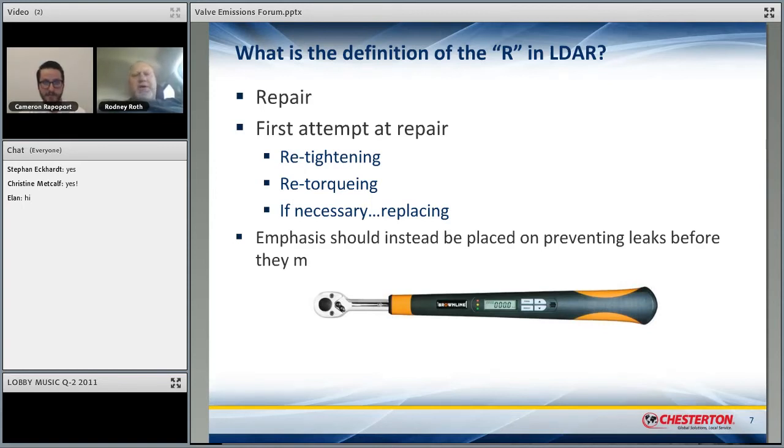And also, too, you have to understand that they may be on quarterly monitoring, and once it becomes a leaker, it becomes monthly monitoring. So instead of doing it every 3rd month, you're doing it 3 times a quarter. Right. You have a lot of chronic leakers. You can drive the frequency of your monitoring more across your entire plant, right? So if you have a lot of chronic leakers, you go over a certain threshold and you were on, say, biannual or annual monitoring, that can get bumped down to quarterly or biannual. You go down that next step.